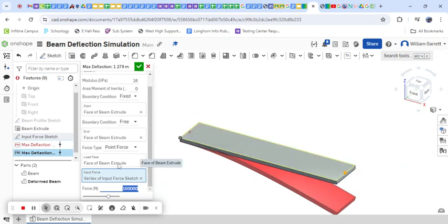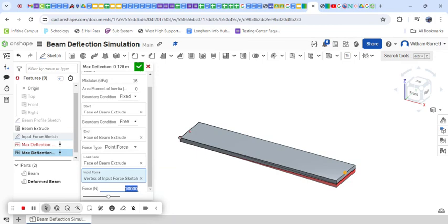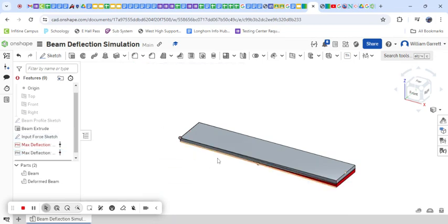So you want to check your value, and you should get a value of about 1 centimeter. Again, you have to do your conversion for that. I'm not going to go through. You can figure out that, determine that value. You should have a calculation value that you're double checking here. I'll get away from this maximum deflection now. I'll go back to that 10,000 we had. Once you do that and you check your answer, and hopefully you have the right answer, if not, go check your maths, get some support, and see what you need to do.